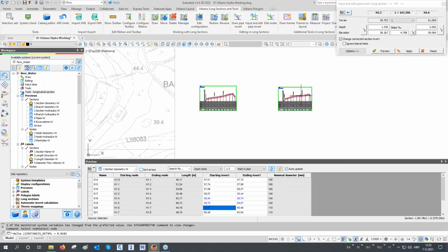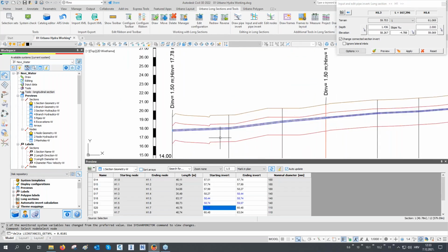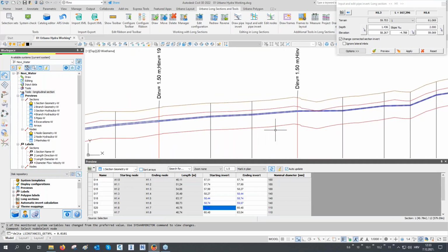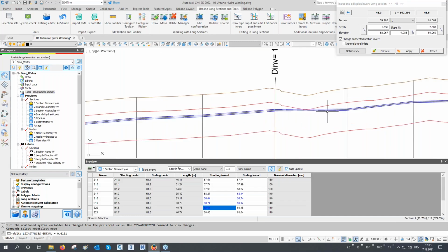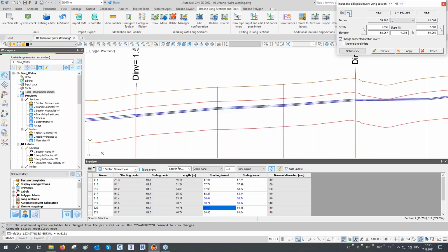Of course, we have also some automatic error detection where you can search for these pipes that are, for example, too low, but I would like to show you this graphical way. For example, here, maybe we can change this as well. So let's again select this part of the profile from this main point to this main point.